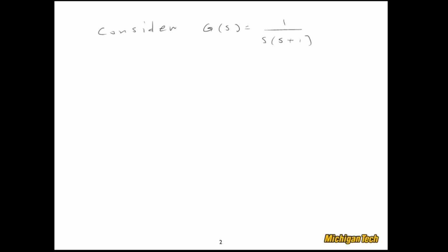And then what we'll do is we'll cycle through different variations of the PID controller. So we'll look at just a proportional controller. That's just Kp with Ki equal Kd equals 0. So we call that a proportional controller. And we've seen a lot of those before.